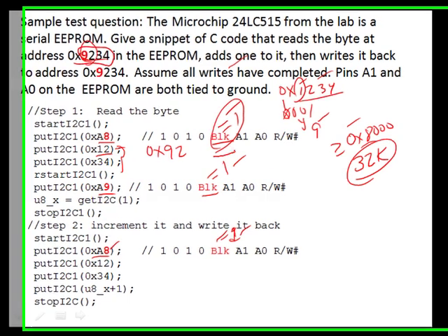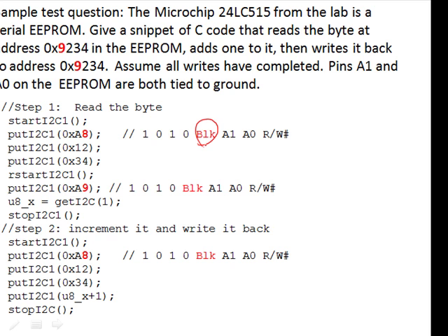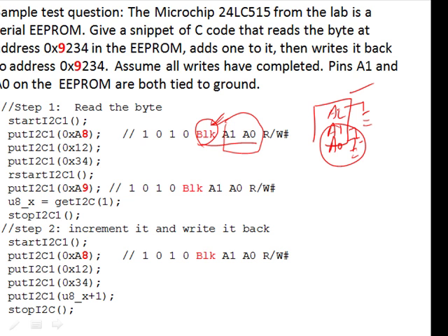We want to point out that treating the I2C device address like this, where we're using this particular bit to mean something in terms of the function of the device and not actually being an external pin, typically that's an external pin on the device, is not standard for the I2C protocol. This is simply how this particular I2C device works. Typically, these 3 bits right here would be reserved for physical connections you would make for the device, but Microchip made the decision to use these 2 bits for physical connections on the device to change the device physical address, and then use this bit here in the I2C address to mean something in terms of the internal functionality of the device, and this is not standard use of the I2C protocol. This is very specific to this particular device.